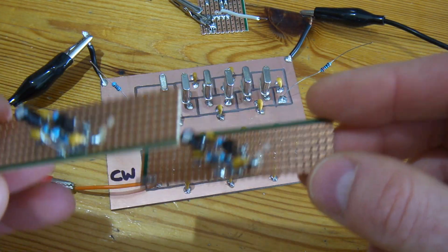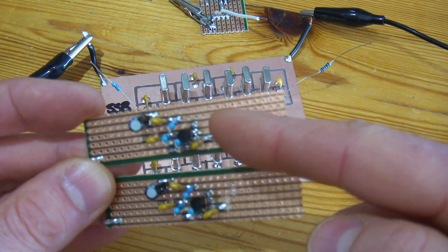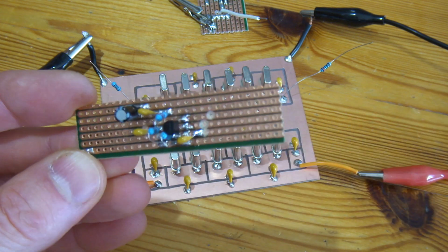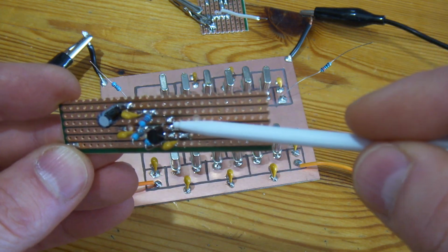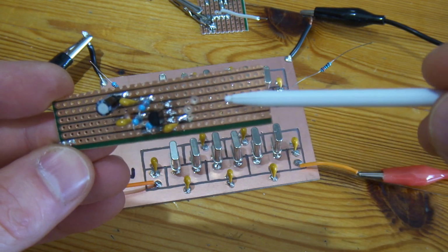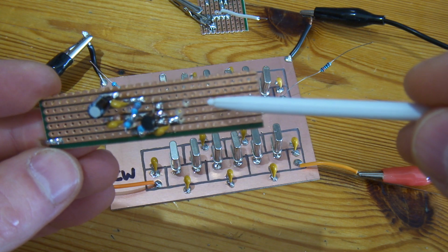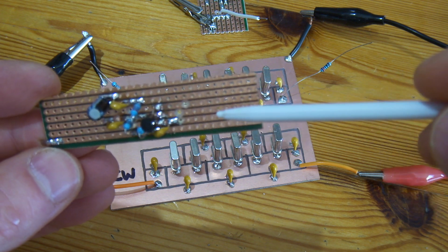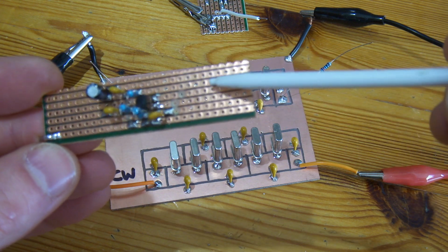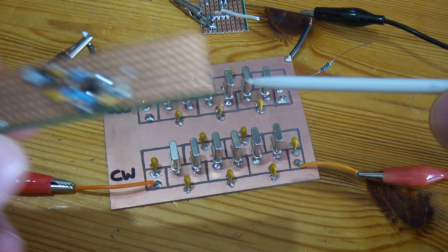What I do need to then work out, and I'll cover that in another video, is what the output resistance is. I'll say impedance, but I'll ignore the reactance components of the IF amplifier. I'll measure the output voltage for a known input with an open circuit, and then I'll put a load on it for the same input, and I'll vary that load until the voltage drops to half the open circuit voltage. I'll then measure that resistance, and I can say that's what the output resistance is. Once I know that, I can start to work out what the turns ratio needs to be to match that resistance to what the two crystal filters need to see.